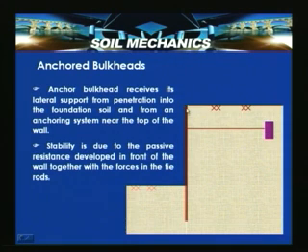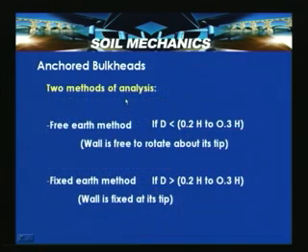Previously, we had a cantilever sheet pile wall without any tie rod or anchoring system, but in order to manage deeper excavations, especially in waterfront structures in the marine environment, stability is ensured by the passive resistance developed in front of the wall together with the forces in the tie rods. These tie rods have to be placed at a certain spacing and should have sufficient length so that they do not interfere with the failure surfaces.